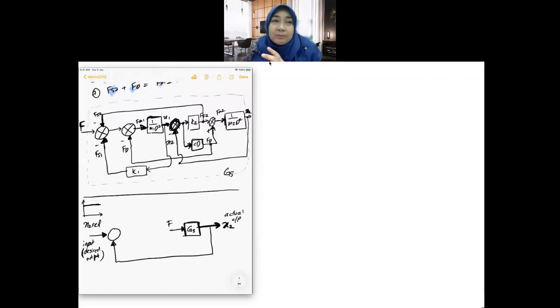All right, so then of course there will be error, isn't it? When we compare this, I put this as positive, this is negative. Normally class, if you read some textbook on control, the summing point is represented as a circle with positive and negative depending on your equation, outside the block, or sometimes inside here. You will put positive here and negative here, isn't it? So it's representing X2 reference minus X2 actual. From there you get what you call the error of your system.